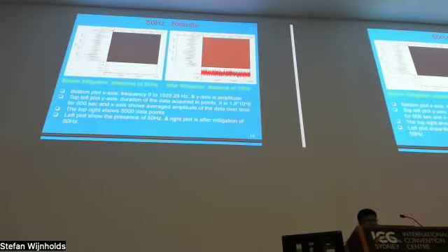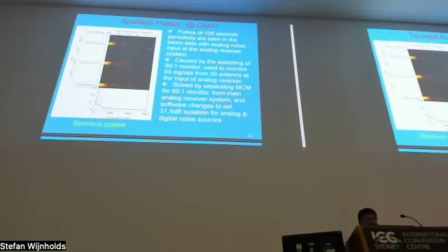So this right side plot shows the 600-second data, and the bottom plot shows the frequency from 0 to 1528 hertz. Then the third one is spurious pulses. Because of that 60-to-1 monitor we have introduced for monitoring and debugging purposes, we were getting some 105-second periodicity pulses. This 105 seconds was matching with the switching of the 60 signals from 30 antennas.